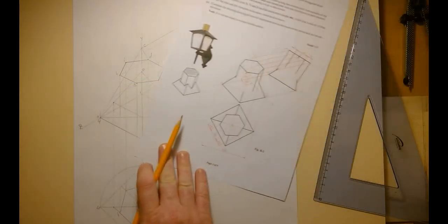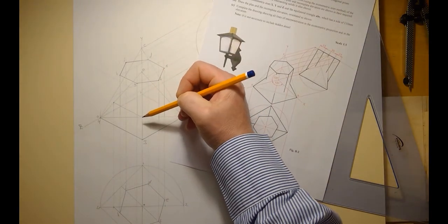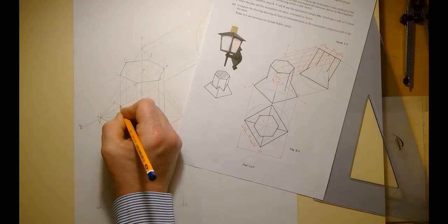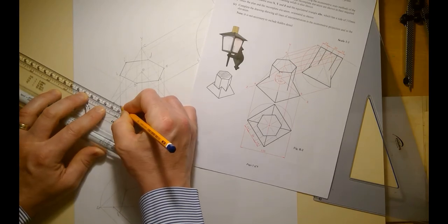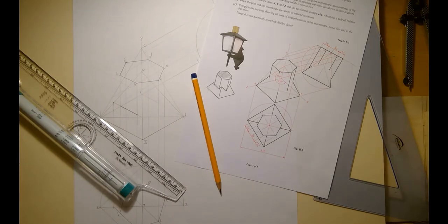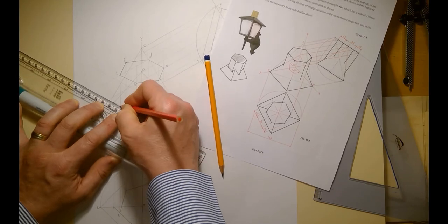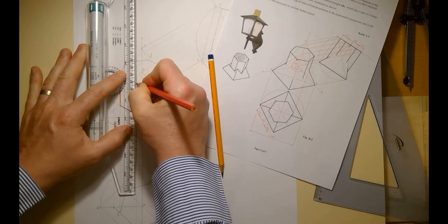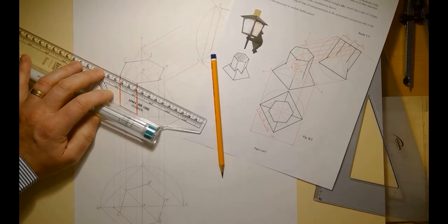okay, so there's that line. Because that line I've drawn in there, I now have it drawn in my axonometric view here, and that's where that cuts off then. Okay, so that point there and that point there. And so that's the front face dealt with. Okay, just put that in there in red so you can see it clearly. So here's that front face dealt with. I'll just go around the rest of that in red.